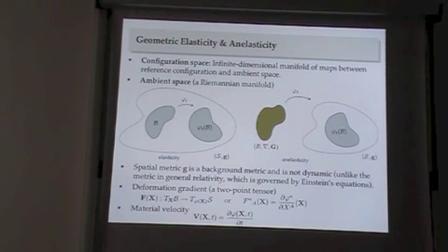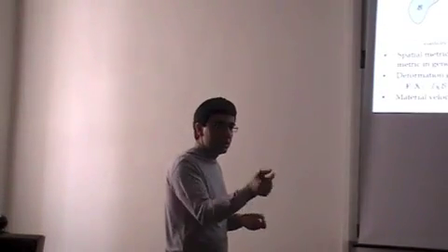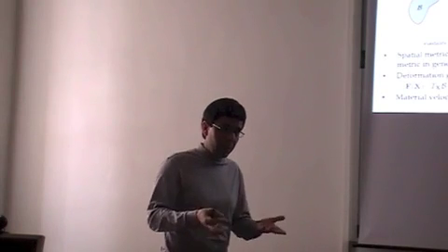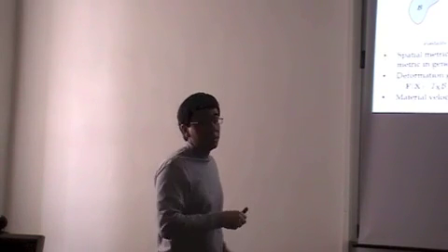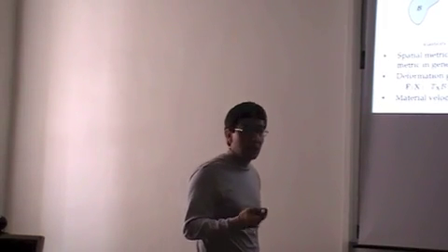Now, let's say there are sources of residual stresses, and depending on the source of residual stresses, eigenstrains I'm going to discuss explicitly, let's say I can find a manifold with some geometry in which the body, by construction, is stress-free. If I can find this manifold, then my problem is transformed to a classical nonlinear elasticity problem. I can intrinsically define a map from a three-manifold to another three-manifold, and if I can construct this manifold, then I'm dealing with a classical nonlinear elasticity problem. And that's how I'm going to solve the inclusion problem.